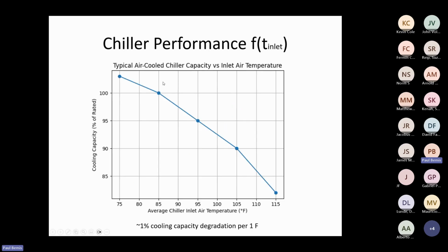So here's chiller performance as a function of temperature. And you see here that the cooling capacity is declining as inlet temperature rises. So down here at 75, 80, on a day like that, it's fine. But these rooftops get hot. A lot of times these rooftops are black. They're emanating solar radiant heat right off the surface. I've been on rooftops measured with an infrared thermometer showing 165.